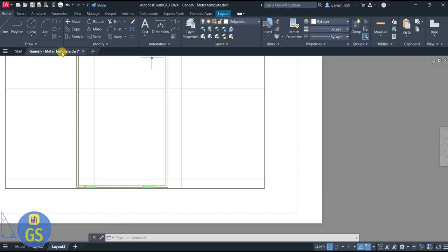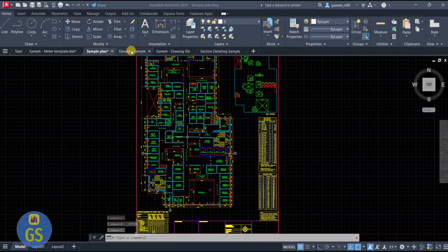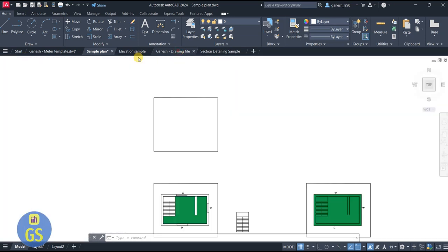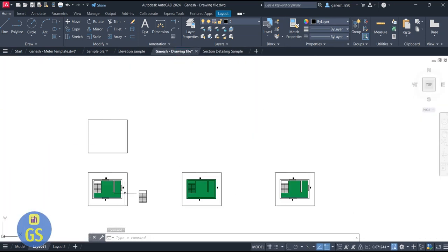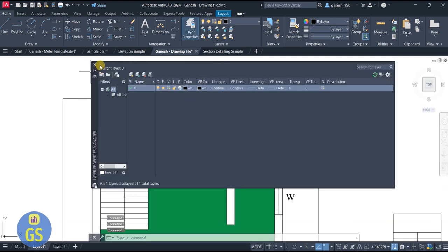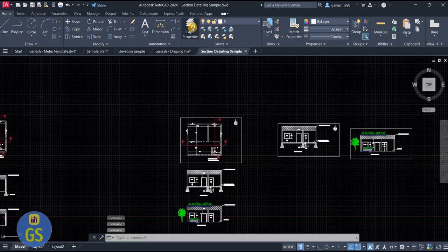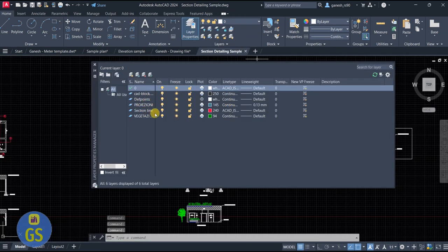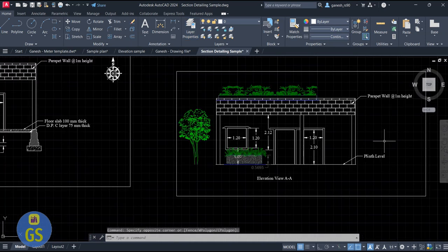So let me show you a few samples. Okay, so I have loaded a few projects. If you see this particular part, this is a simple line sketch with shading all done. We are doing it with layer options. So you can control the layer options, various layer objects you can do. If you're going for a big scale, these are the objects. Again here you can see I have added a number of objects in the plan. Different layer options I have added, for section lines or property lines or CAD blocks. According to that, the objects are controlled here.